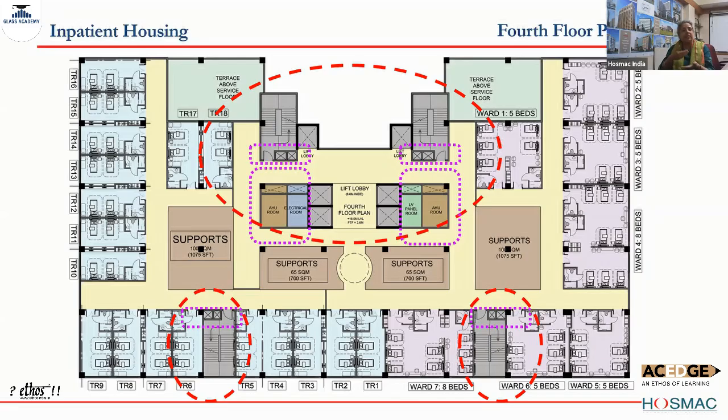A good practice is to always give lift lobbies to lifts. We try to save spaces in hospitals, and we try to just push the lift back a little and give the opening of the lift onto main corridors. This doesn't work. So we should try and be considerate of our vertical movement in combination with horizontal.